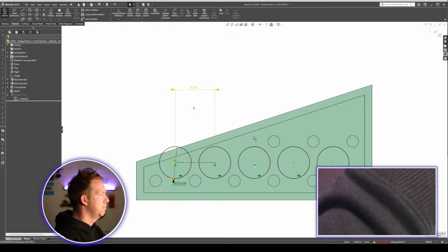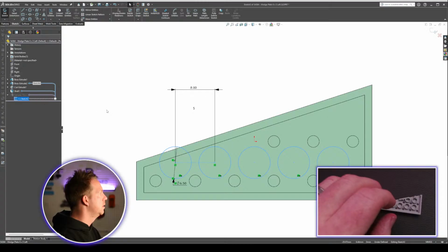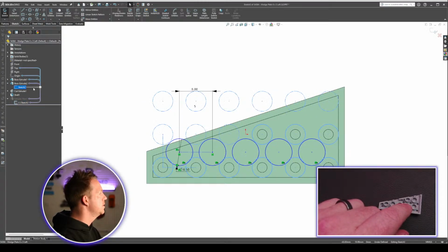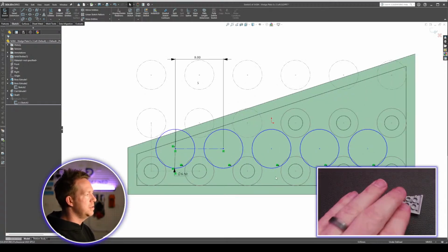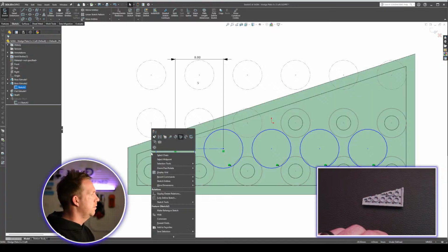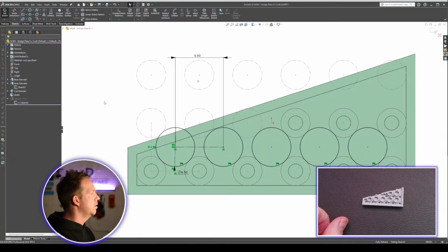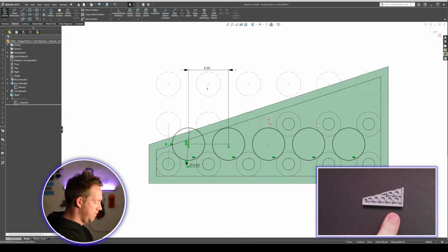Oh, don't need that, because this one is already referencing some of the other sketches we've got, these ones here. That's handy. And it's handy to use some other references there, because instead of creating new geometry or new relations or sketch points, I can right click this one, select midpoint, hold Control, make that horizontal to get that position right. So that's my 5 holes across the bottom.